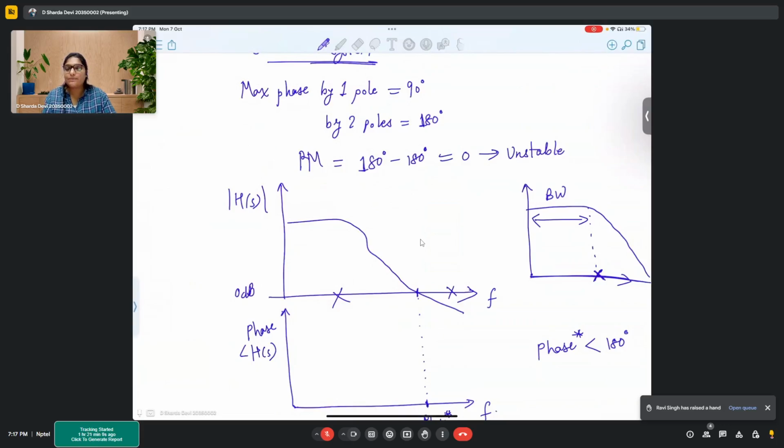So that is stability. If it is very near to the crossover frequency, then we might get into the zone of instability, right? So we want the poles to be quite far apart. And also, your second pole should come after the crossover frequency.